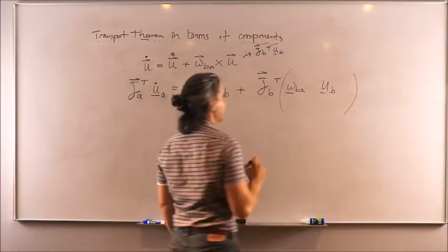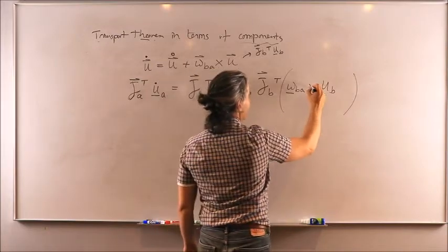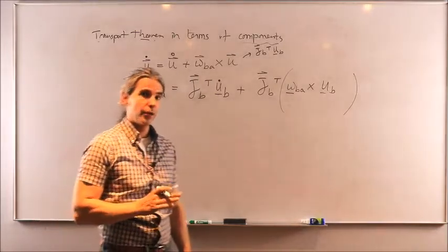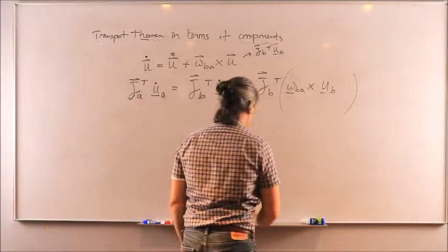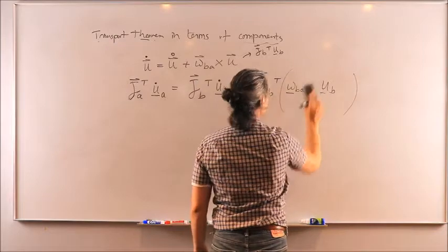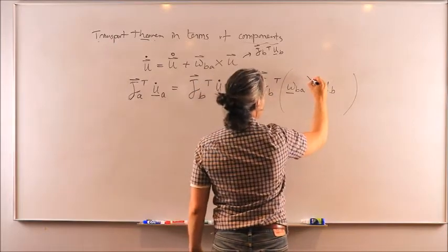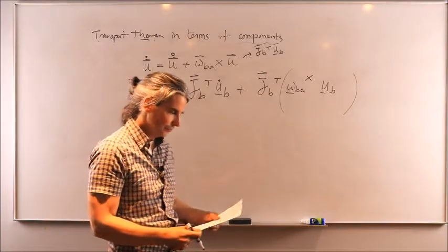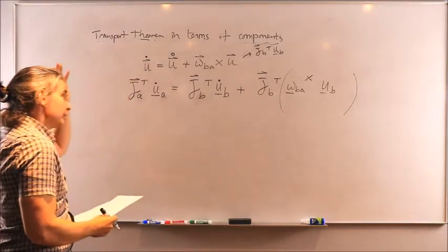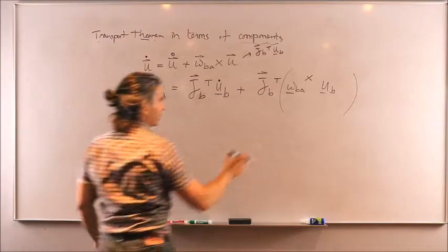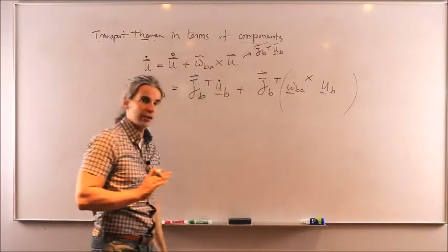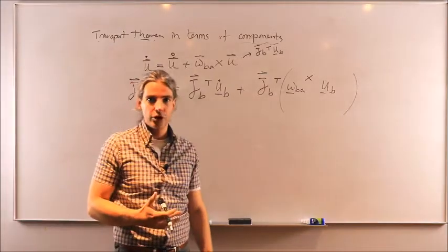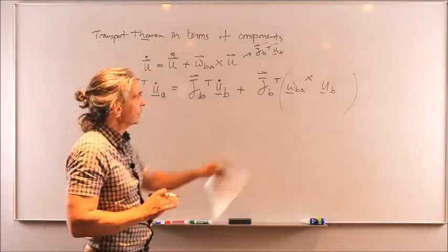Now here, I cannot use the cross product symbol because the cross product is a vectorial operation. What I have to do instead is use the skew-symmetric matrix operator, which applies to components. All right? So never do cross product of two matrices. There's no such thing as a cross product of two matrices.